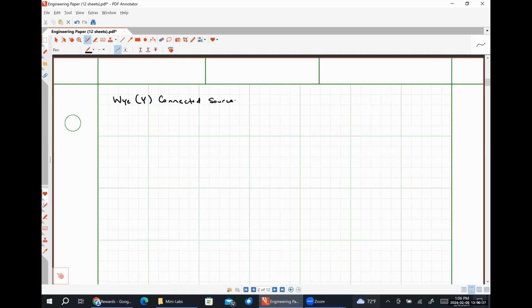So I'm going to also redraw it in a way that helps me sort out the circuit analysis part of analyzing these 3-phase circuits, okay? So I'm going to start with the neutral conductor directly in the center. And I'm going to make a note here that this is technically optional. So we don't necessarily have access to the neutral terminal, even if our source is Y connected.